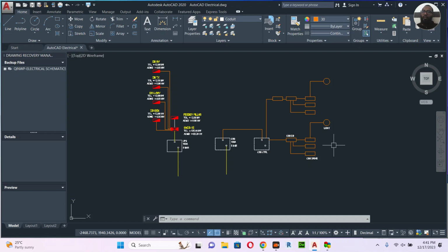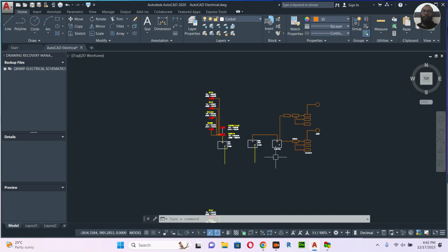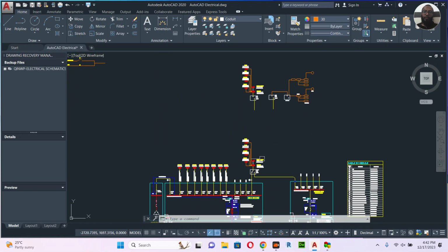If it is a regular system, directly DB to light, light to switch, finish. But if it is specialized, or a DALI system or any other home automation system, anything you see, like a specialized controller through remote or through internet or through mobile application or anything, 100% there will be a controller. So don't forget that one. There will be a controller.